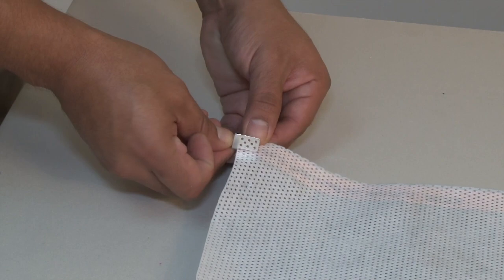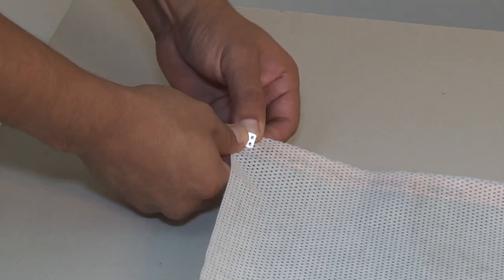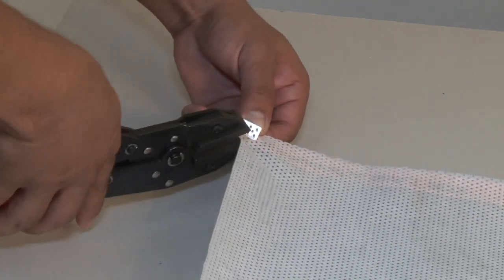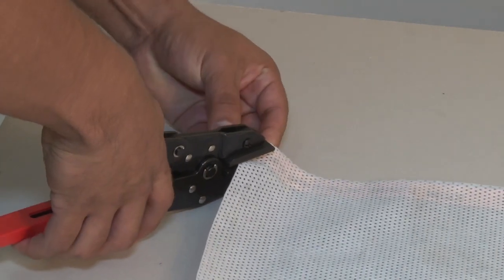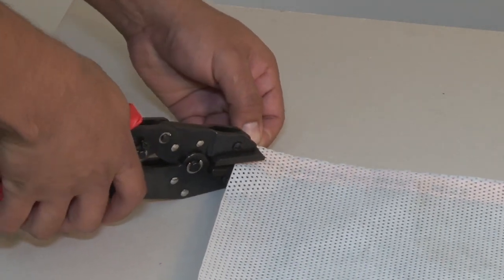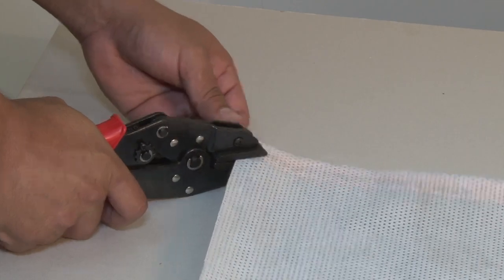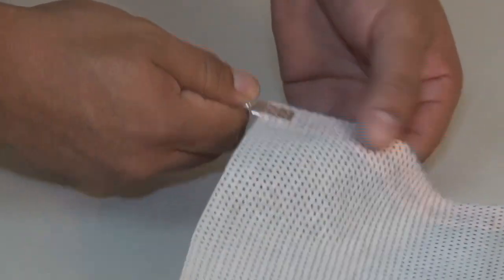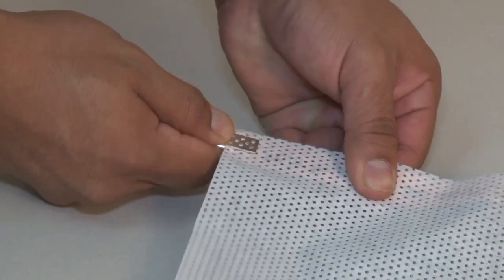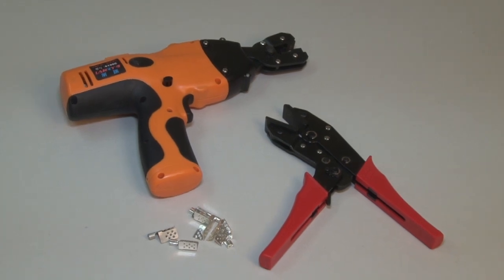Splice connectors can be crimped to the copper conducting strips using regular slip joint pliers, linesman pliers, or similar pliers with wide flat noses. To ensure the best contact, verify that the crimped connector plates are parallel and the other surfaces are 1/8 inch apart or less. For best results, use a professional crimping tool.